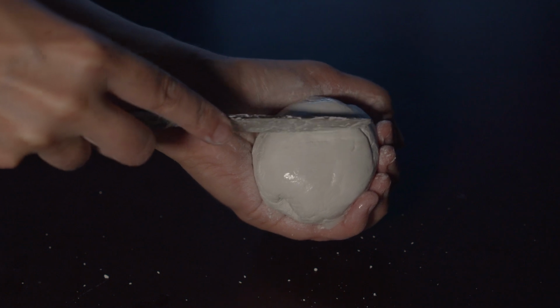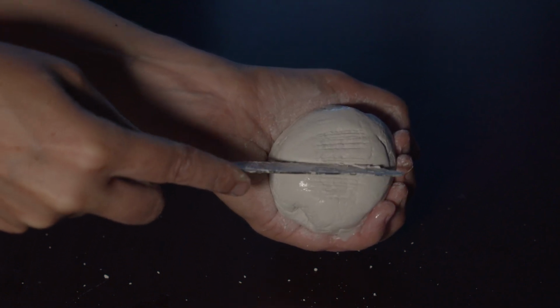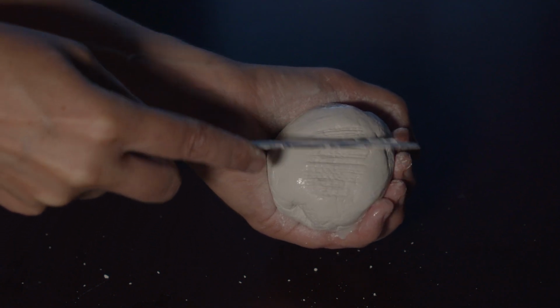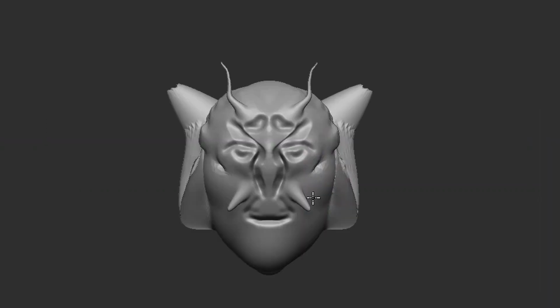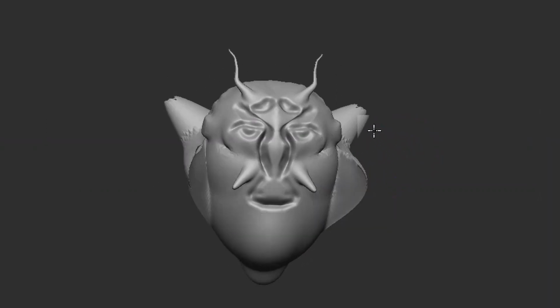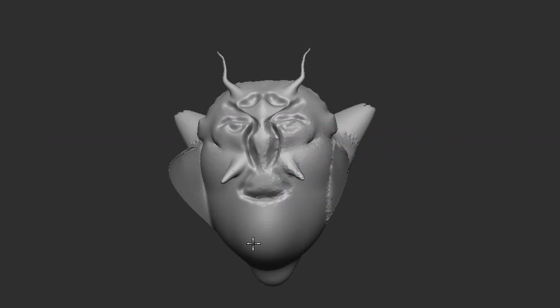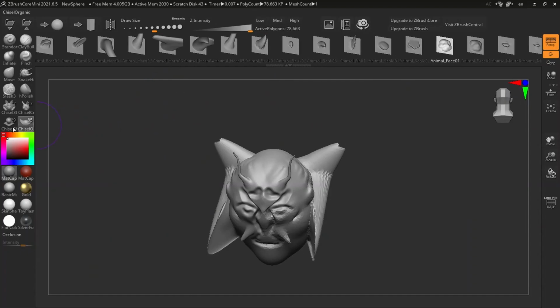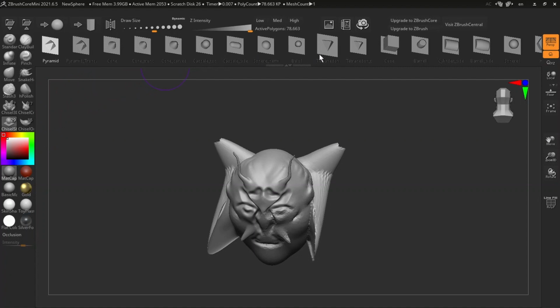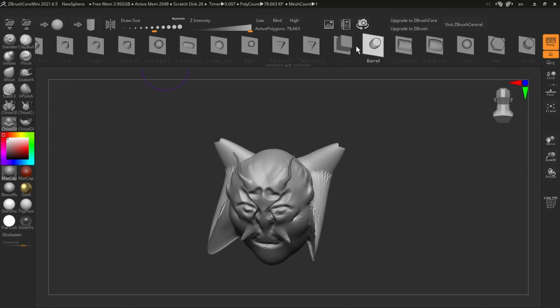Most organic forms have some sort of little deformation on their skin, and we can fill it up by lowering the intensity and using some chisel. Like this scale tree, we can add a little texture to the side cheeks. So this distortion looks like some form of skin. Here we have 4 different chisel groups. In the chisel shapes, we can find the squares, and if you want to make something much more hard surface, we can always use them.